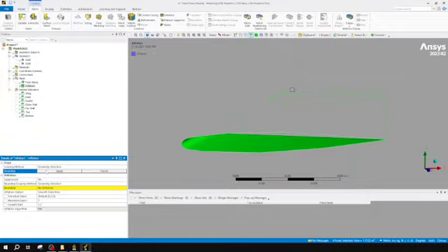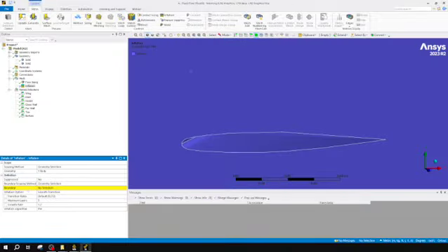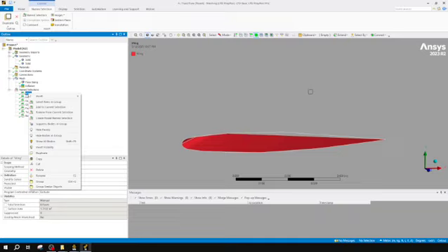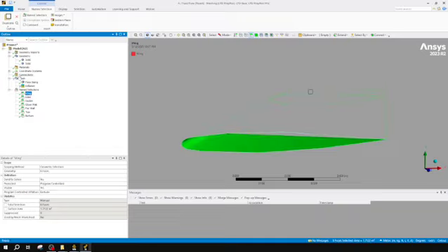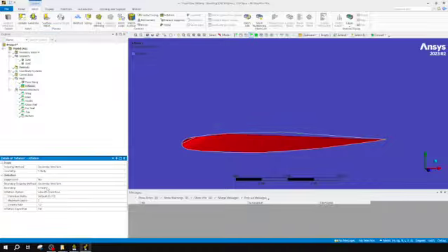So actually, for my geometry, I'm going to go over to select body, and I want the entire body to be my geometry. And then my boundary is when I come here to wing, select items in my group, go back to my inflation, and that is my boundary. I'm going to have about 20 layers. 20 layers makes sense.